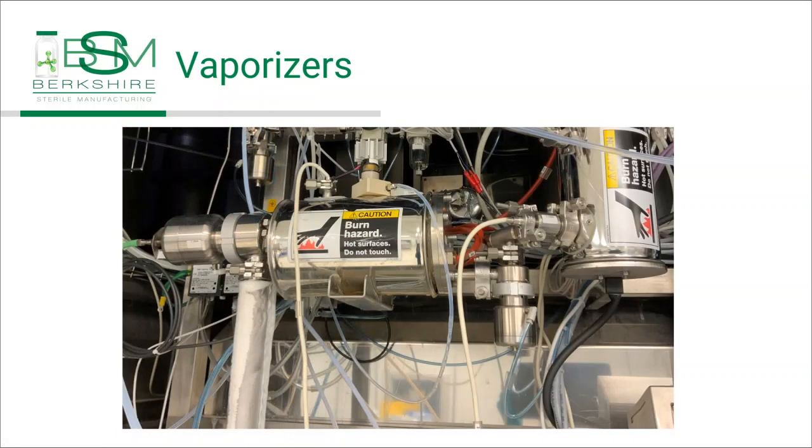Here's another vaporizer. This one's a little more complicated, a little more sophisticated. This vaporizer here has a preheater for the air coming in. This is the preheater that preheats the air coming into the system. The air then is pumped into the vaporizer here, and it's hot air. On top of the vaporizer is a small diaphragm pump. That's this right here. The diaphragm pump is pumping from a reservoir.